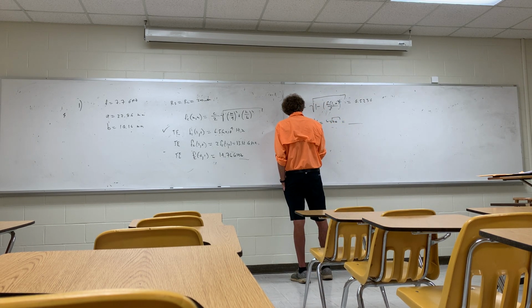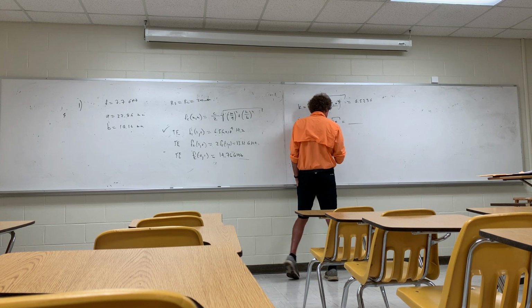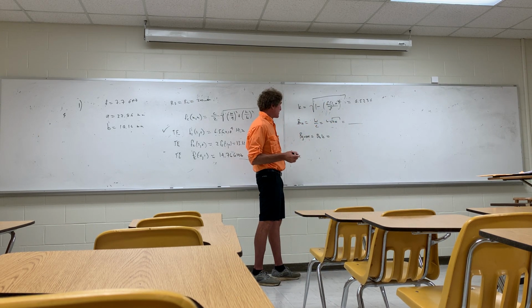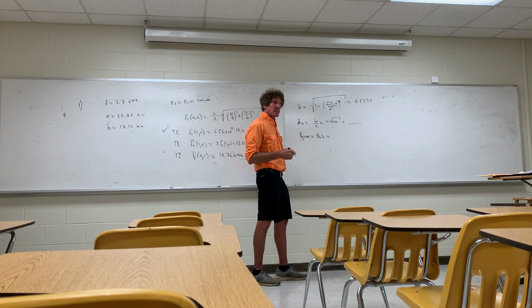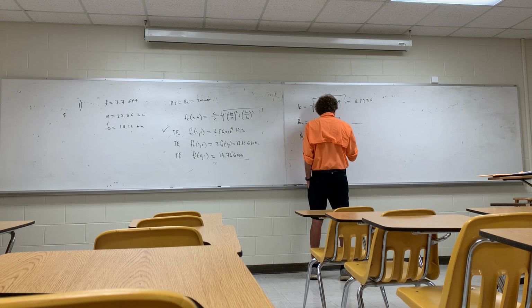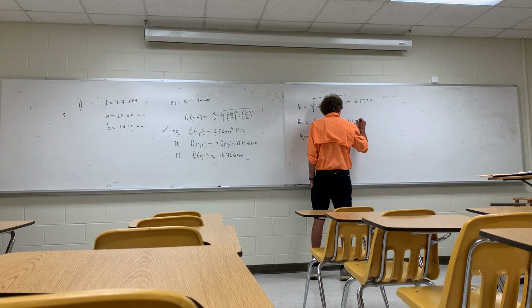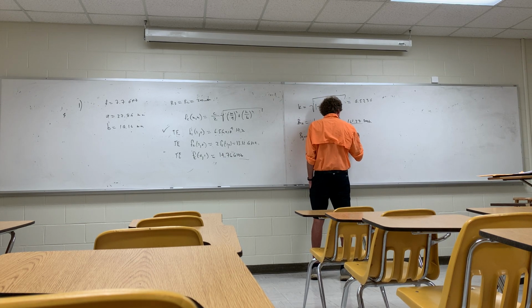Anyway, beta in the guide is going to be beta unguided times K. And you can give that if you want. 84.44. Beta unguided? Beta guided. The other one is 161.27. And that would be radians per meter. And this is 81, did you say? 84.44. That would be radians per meter.